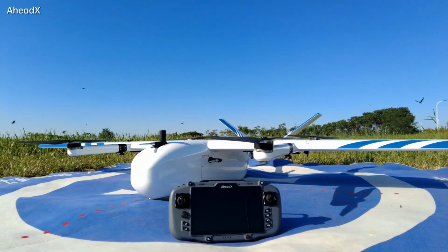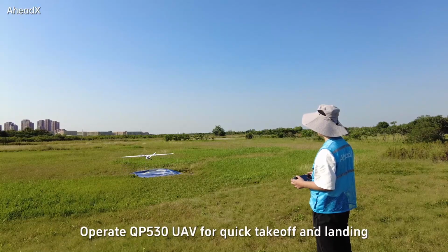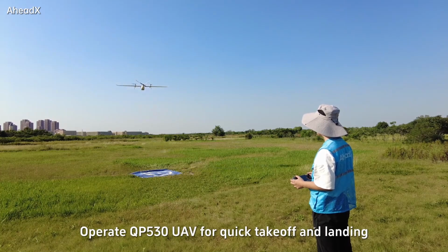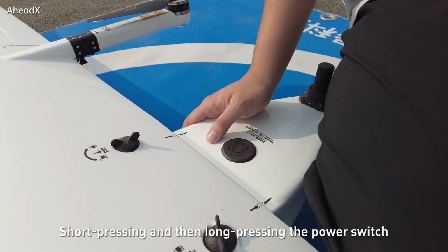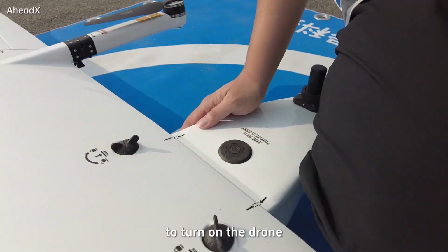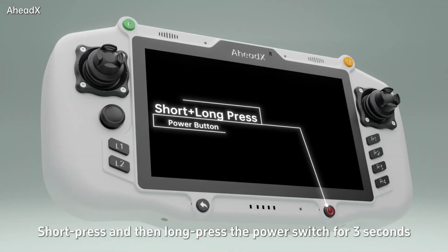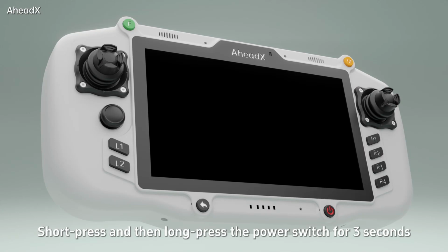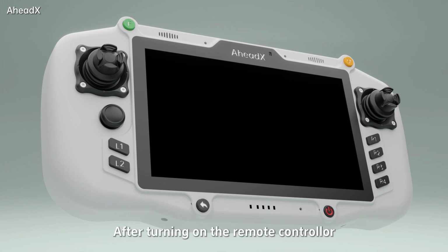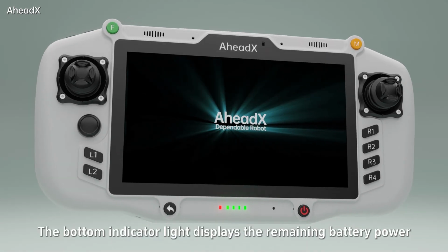Hello everyone. In this tutorial I will introduce how to use the H30 RC to operate the QP530 UAV for quick takeoff and landing. Short press and then long press the power switch to turn on the drone. The remote control follows the same steps. Short press and then long press the power switch for 3 seconds. After turning on the remote controller, the bottom indicator light displays the remaining battery power.